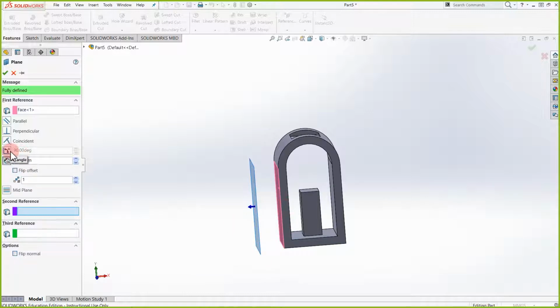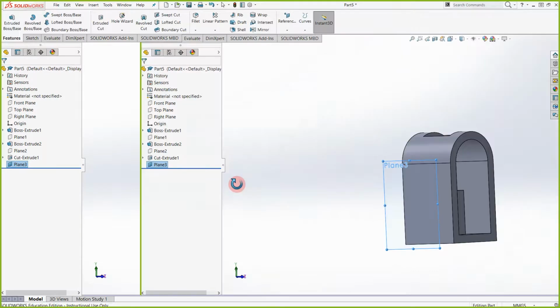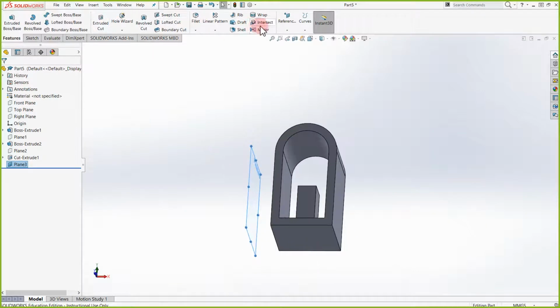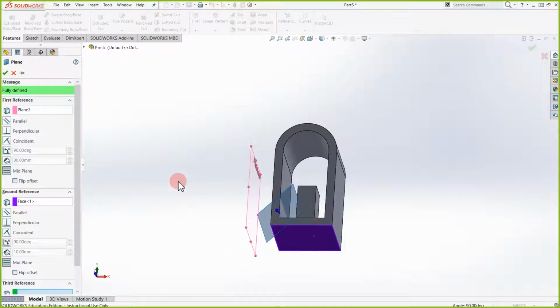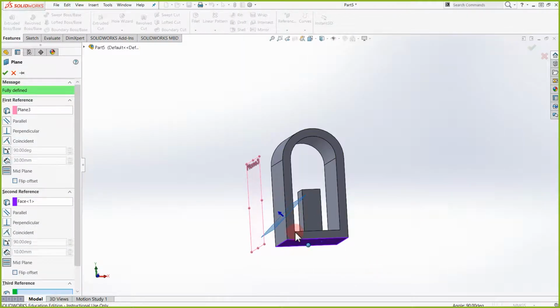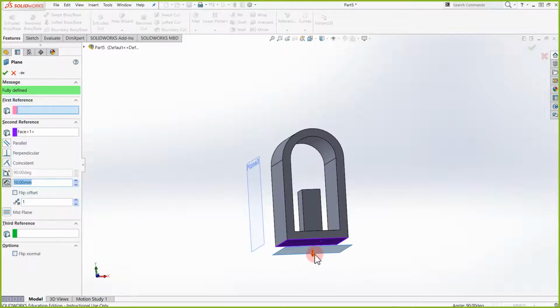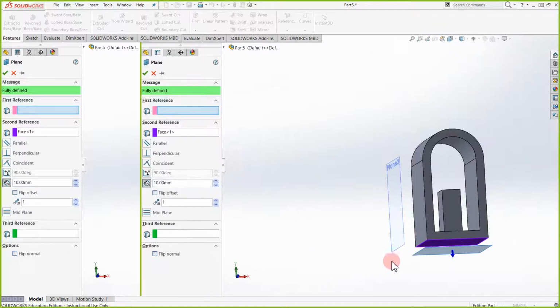If I wanted to angle it, I could put it on an angle. Depending on what I need, I'm able to play with those reference planes. Accept. And now I have one over here again. If I want to do the offset reference, I just choose any face I want, the bottom, for example. Why is it doing this angle? Because I did this face and this one. But if I don't want it, I could just go back, delete this, and I do have the option again for the offset. All right.